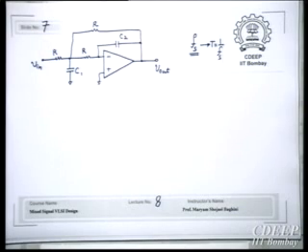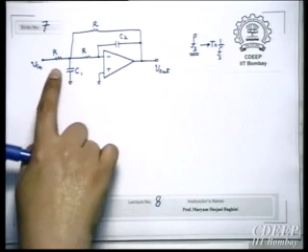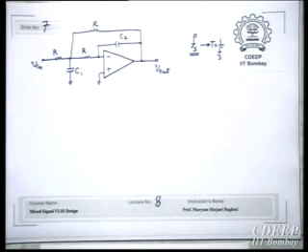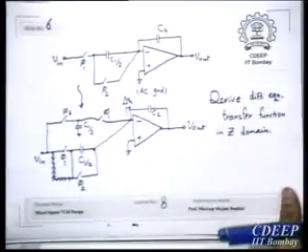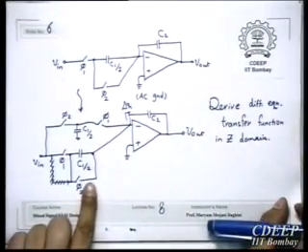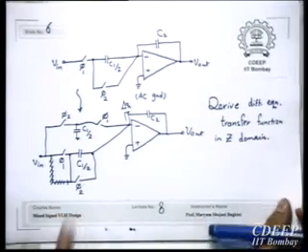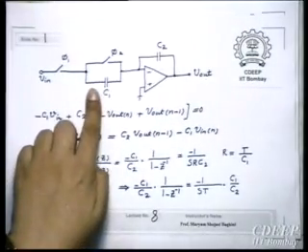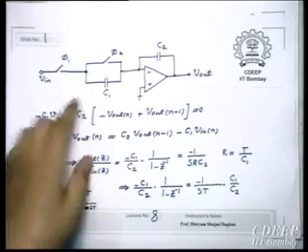So simple. So what we do, for example, you want to implement R, right? So we need to implement R. Now it depends which approximation you want to use. For example, if you want to use bilinear, it means you need to replace it by this, right? If you want to use backward, then it means that you need to replace the resistor by this. Therefore, it's straightforward.